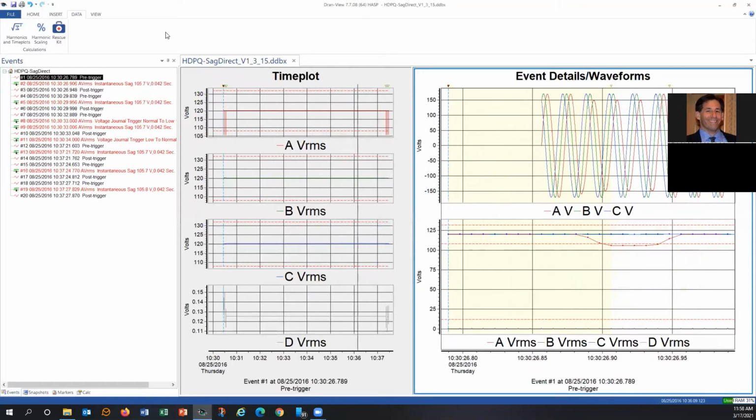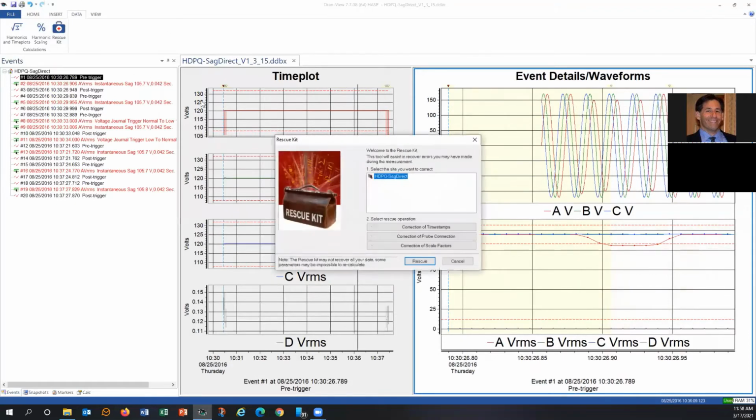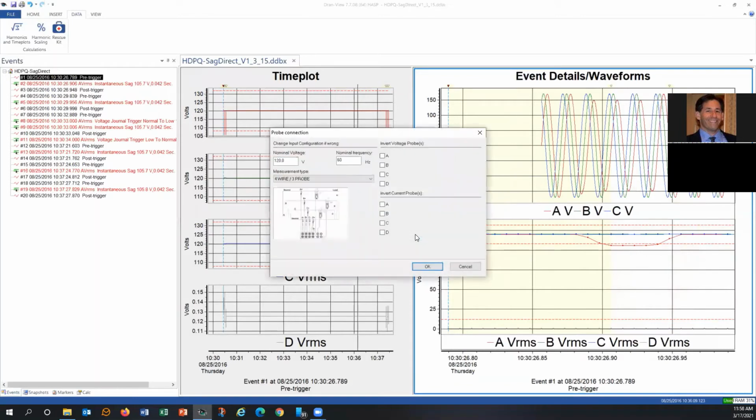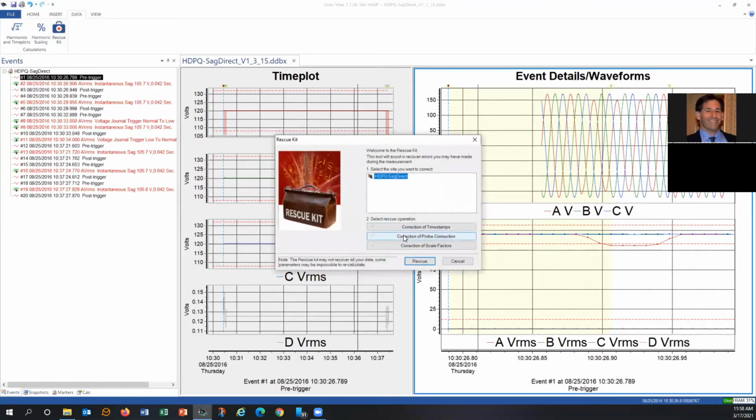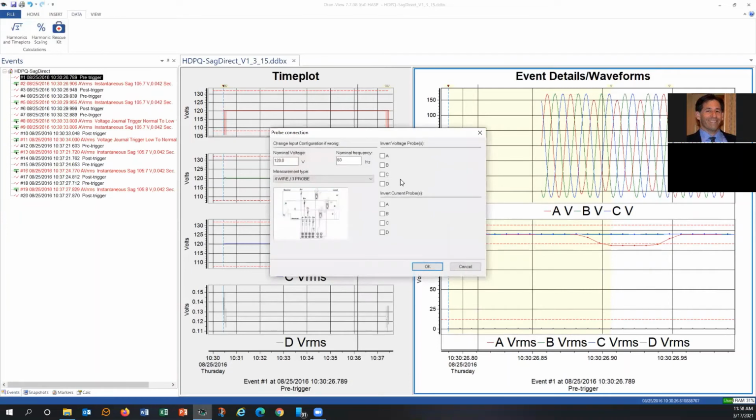All right. If I go back and I go to rescue, or B voltage rather, and I flip B again, my B voltage, click rescue, it's going to flip back again now. More appropriately, these are usually used for currents because those are more common to have a current connection reversed and flipped. So that's the power of the probe connections and the voltage connections. So you can invert voltage, you can invert current, again, primarily to undo wiring mistakes.